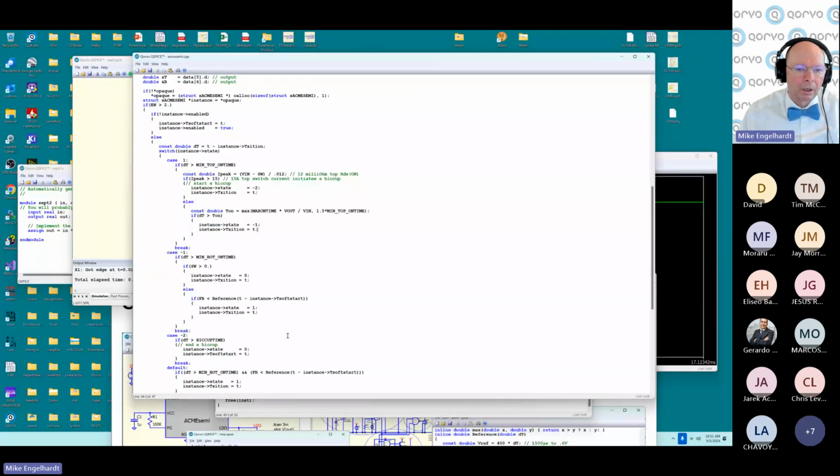And then if you start the cycle on demand, what you end up with is a constant on-time controller that's intrinsically stable, doesn't need an error amplifier, and it's as stable as a crystal oscillator. It's basically the best switch mode power supply I know of how to make.